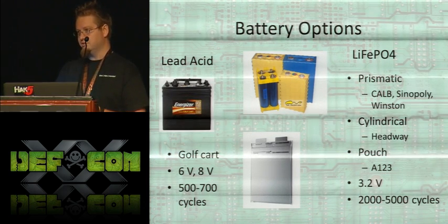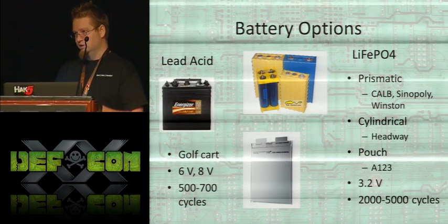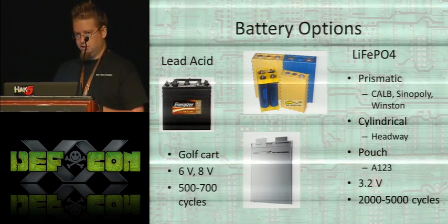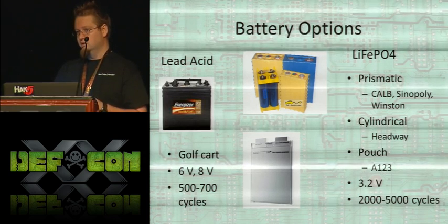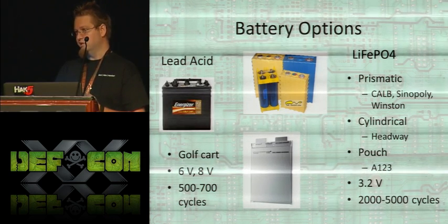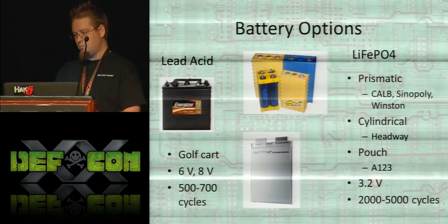Because they're designed for traction uses, they'll last lots longer than the marine deep cycles that I used. They last about 500 to 700 cycles, which is 2 to 3 years. Depending on your usage, some people manage to get 5 to 7 years out of them.